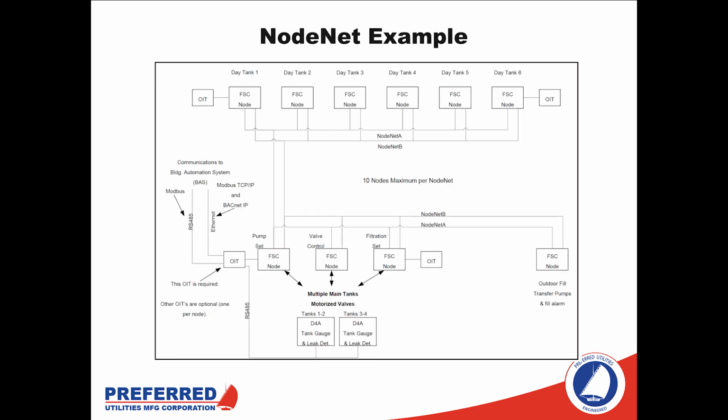Here's an example of just one setup where we have multiple day tanks at an upper level communicating with main tanks down below, transfer pump set, we have our connections to the building automation system, and everything is talking to each other.